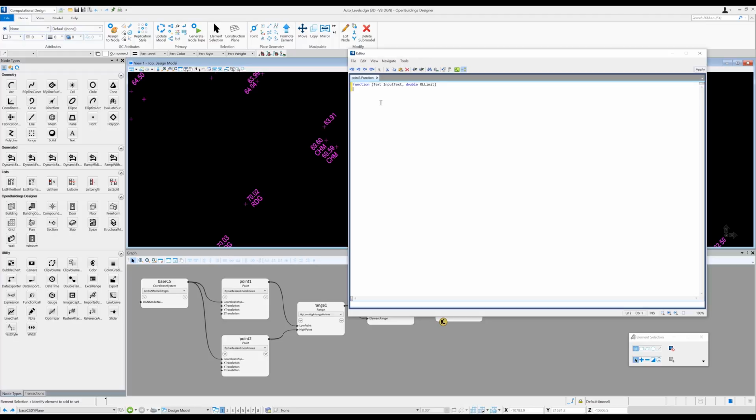We close the brackets, and then we open and close curly brackets to contain our function. And now I can start our function. My approach is to always list my output as the first line of my function. In this case, it'll be a point called myPointList and equal that to an empty container with an open and closed brackets followed by a semicolon. Then I'll start a loop to run through the input text. Typing for and tapping the tab key a couple of times will auto fill out the line string. And here I just change the count to inputText.Count with a capital C.